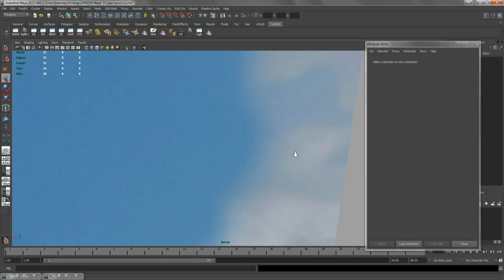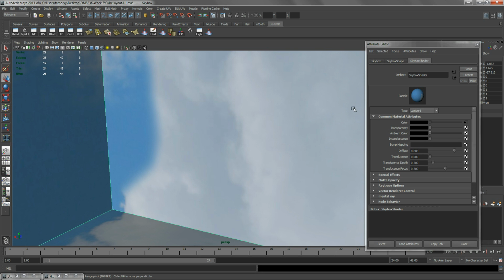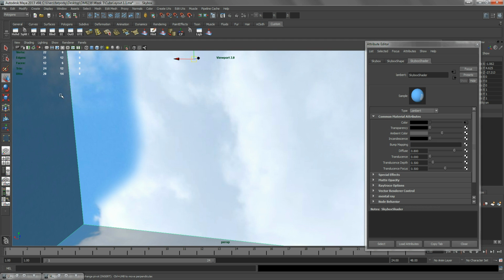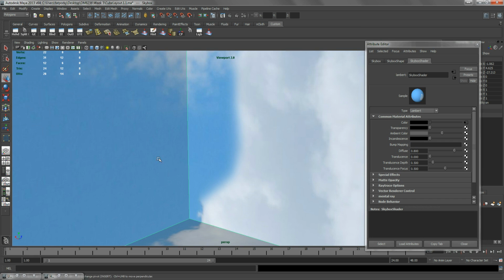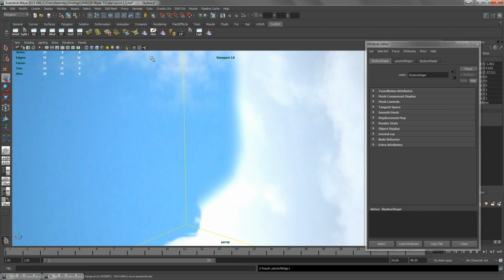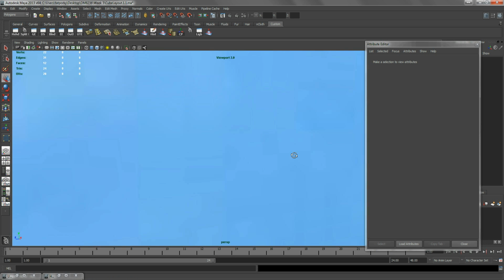And just to make things better in Maya itself, because right now if I were to look at this, it's really quite distinct. So what you can do is crank up the ambient color. You can see it better in Viewport 2.0, but again you're gonna see this awkward shading, and this is because it's based on the normals. So you can go ahead and select your geometry, go to normals, soften edge. Alright, so that way it will kind of blend nicely.